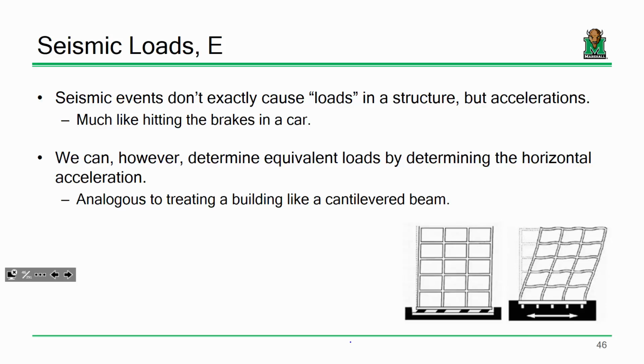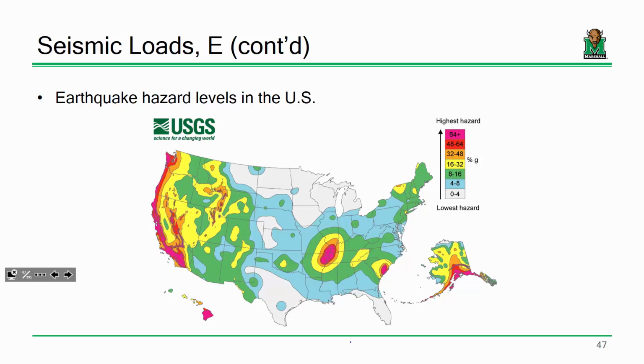Something sound good? Okay. The only thing I'll point out is a seismic problem is basically distributing seismic forces based on Newton's second law. A building has a certain mass, an earthquake puts it under a given acceleration, force equals mass times acceleration, and that's basically all there is to it.